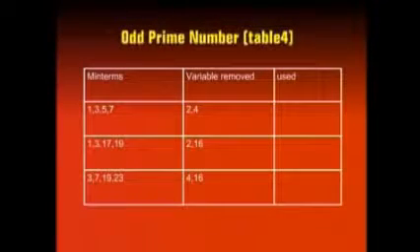The results of the comparisons between two terms in table 3 are represented in a separate table referred to as table 4. The first column lists the terms that have been compared together to eliminate common variables. So terms 1, 3, 5 and 7 form a single term eliminating variables C and D, forming the product term A bar, B bar, E. The comparison terms 1, 3 and 5, 7 are marked as used in table 3.